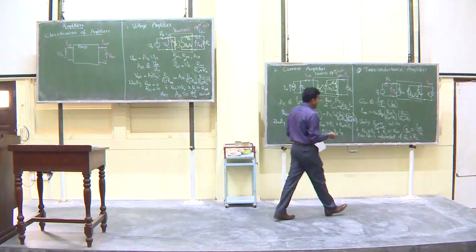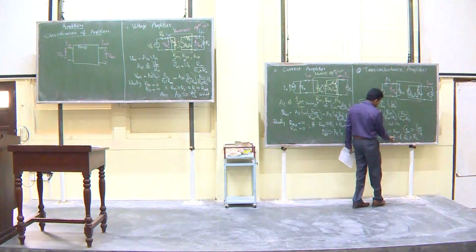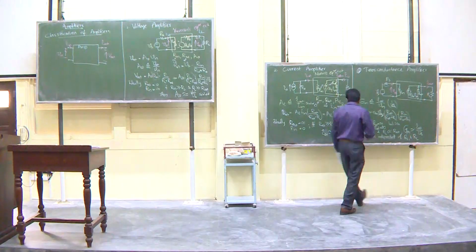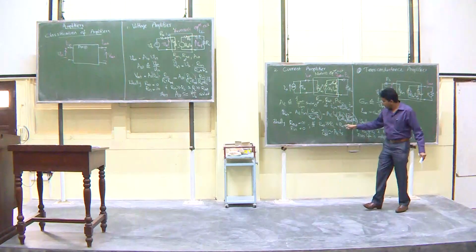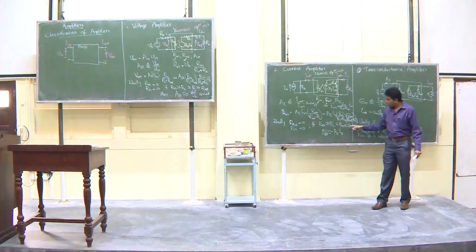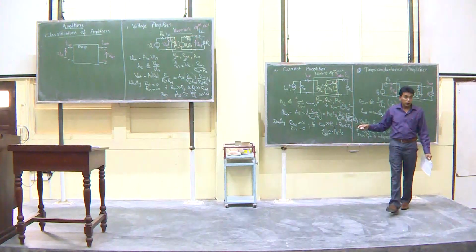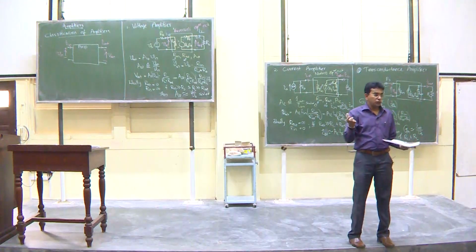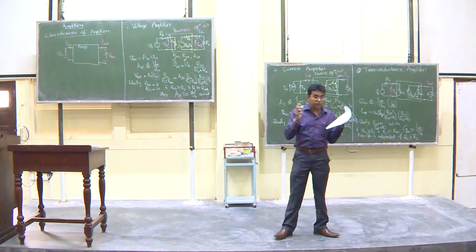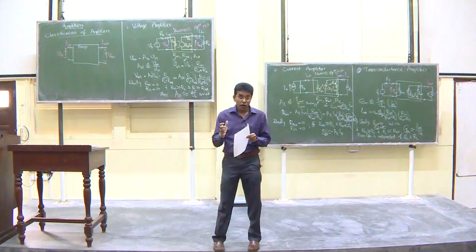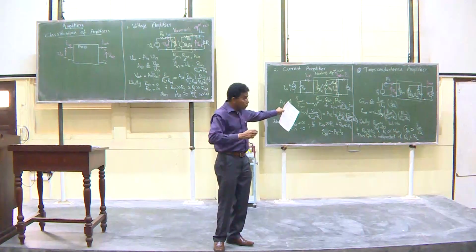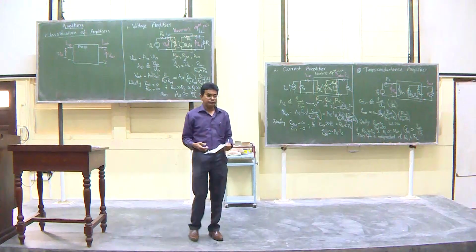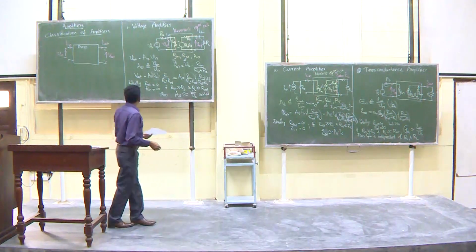Right. So the other circuits are also the same. When you have these conditions met, then they don't depend on RS and RL, which we don't have control over. They are external things. Therefore, we as engineers design these circuits to be as close to these ideal conditions as possible, so that we don't have to worry about what we connect there. That's the purpose.